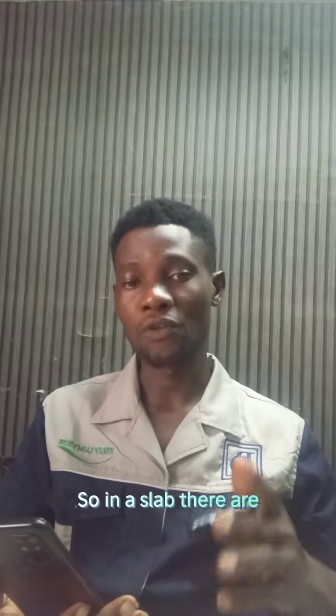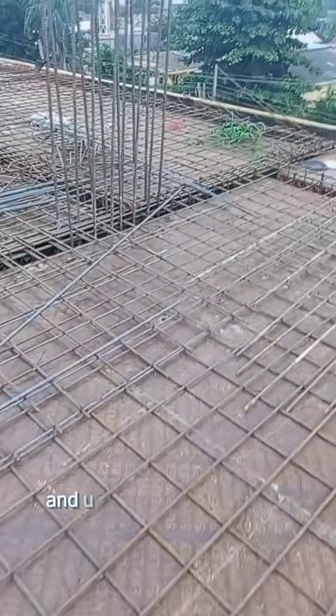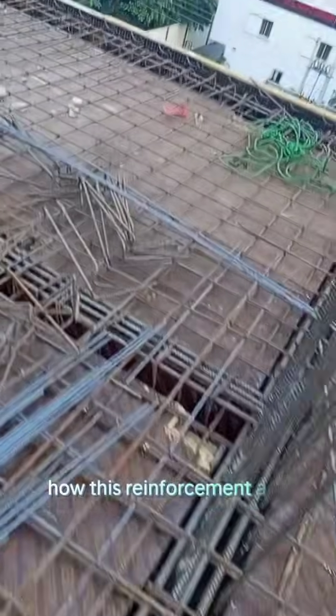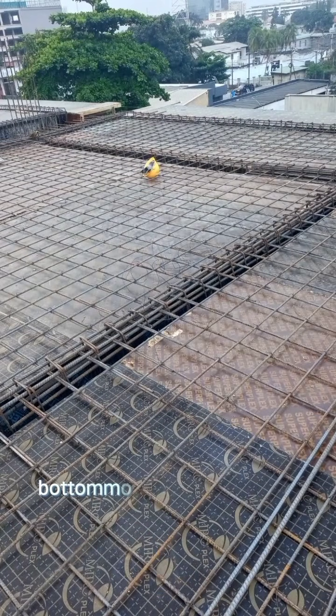So in a slab, there are 4 different layers of reinforcement. Those reinforcements are the ones that are given those names. I'll just explain it in this video and use a structural drawing to explain how these reinforcements are arranged. So the B1 can also be called BB, that is bottom reinforcement. The bottommost reinforcement in a slab is called the B1 or the BB, that is bottom.